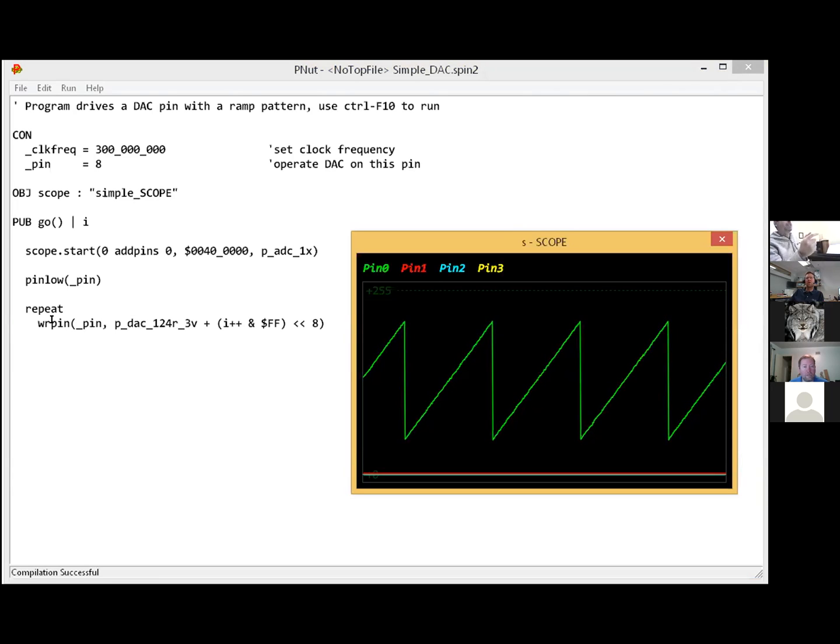And then we have to shift it left by 8 because there's 32 bits in this data that goes to the mode register in the pin. And it so happens that the low-level pin stuff is shifted up by 8 bits from the bottom. So the lowest 8 bits in that whole 32-bit frame are where the smart pin modes are. If you don't want to do any analog stuff, you only need to write values which fit into 8 bits, which become simple, non-augmented 9-bit values in assembly language.